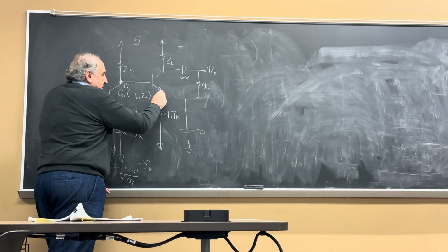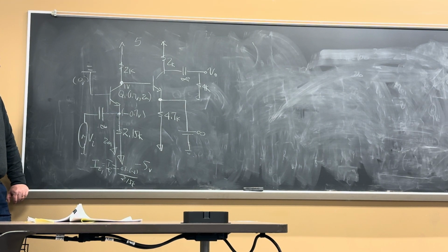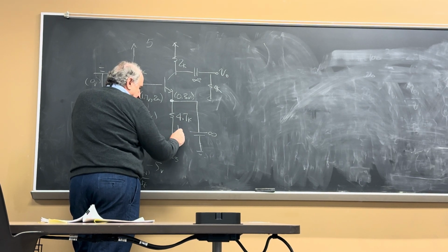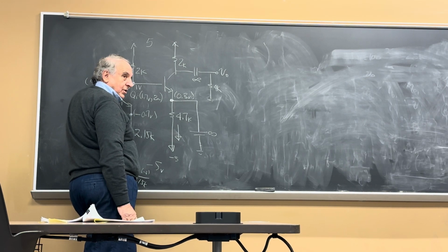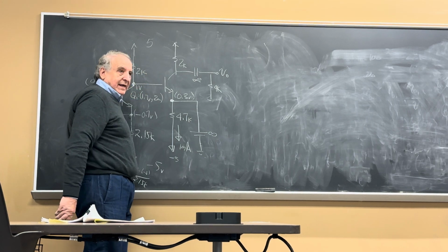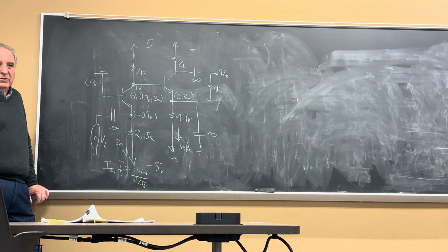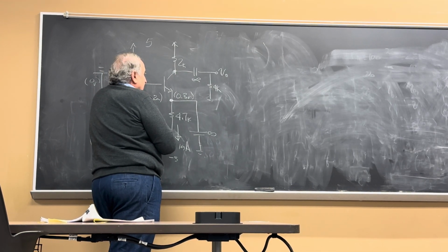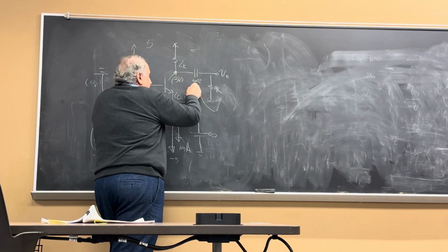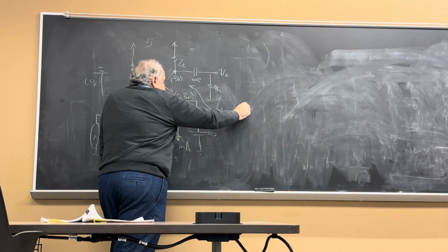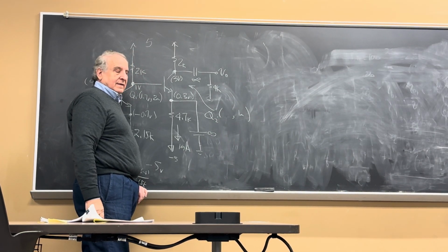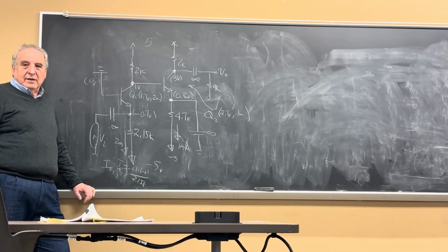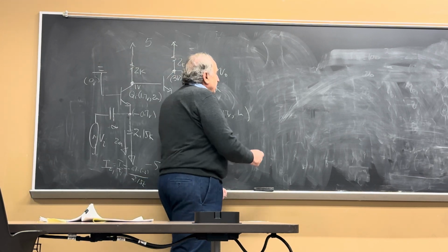Okay, this is 1 volt. What's this voltage? 0.3, right? And this is -5. What's this current? 0.3 plus 5 over 4.7. So, 1 milliamp, right? 4.7 volt over 4.7 K. Okay, 1 milliamp. What's this voltage? It's 5 minus 2. That's the 3. So what's the Q point for this? 3, 1 milliamp. 2.7 volt, right? Now it's easy. That's a two-stage amplifier. Now let's do the AC load line on Q2.